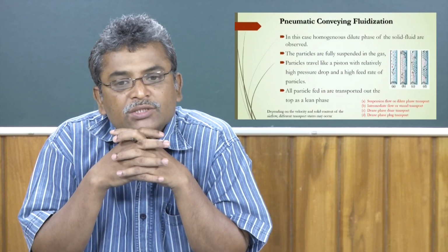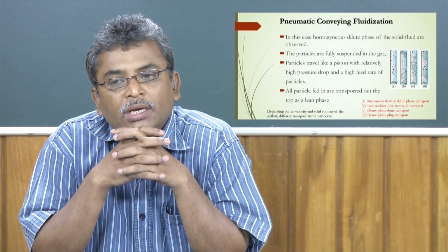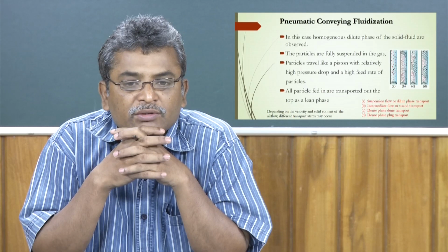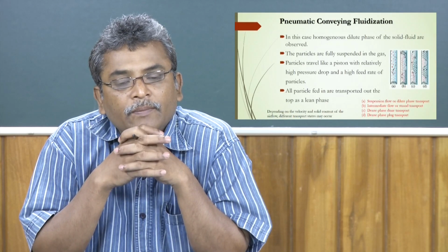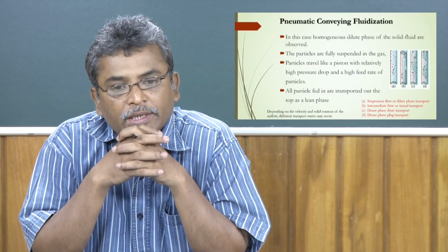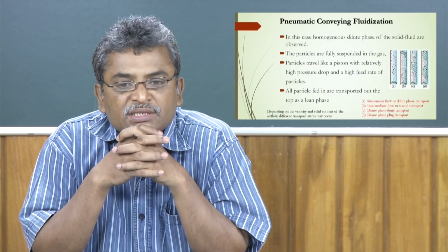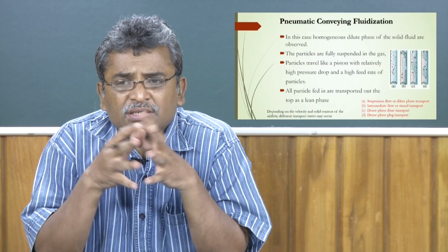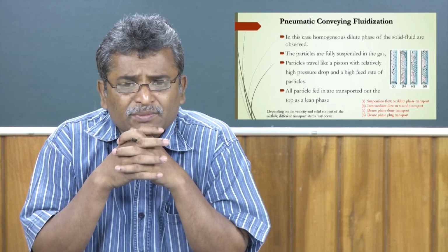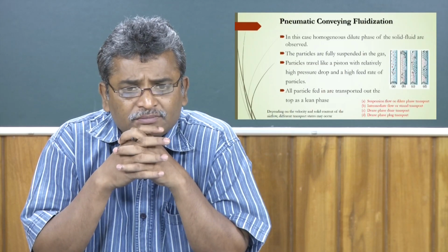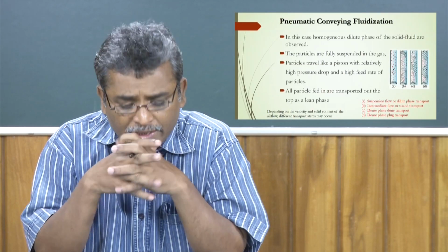Of course, in this case also, more than 20 times the terminal velocity of the solids, the fluidized bed will be operated here. Now, all particles that are fed in the bed will be transported out the top of the bed as a lean phase here.